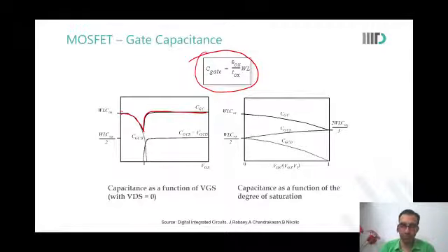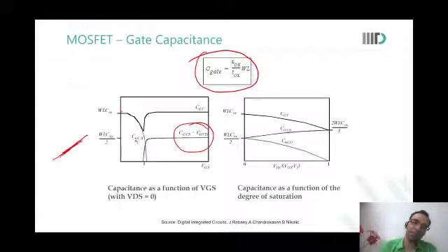So what is this lower graph then? These are the two components. This is the gate coupling with body, because the depletion region was coming into the picture. As soon as the inversion layer is formed, there is no further coupling between body and gate. Now the additional charge comes from the source and drain regions. Remember, in the inversion layer, we said that in MOSFETs, the source and drain will give the additional charge even at very high frequency.